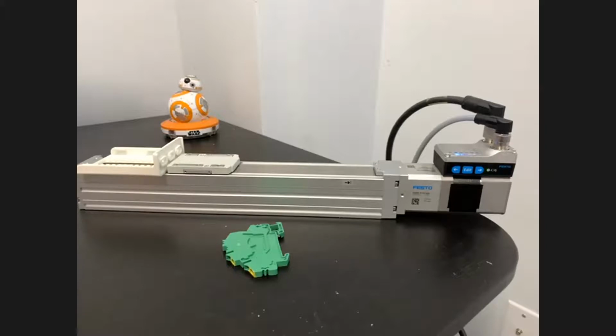Now that you mentioned monitoring, what are the capabilities of this system? With a servo press, you can do window control for when you start to touch the part, or even envelope monitoring through the press cycle. What are some of the features in this simplified motion series? Is there a min-max force? Can you do windows, or how do you visualize any sort of data?